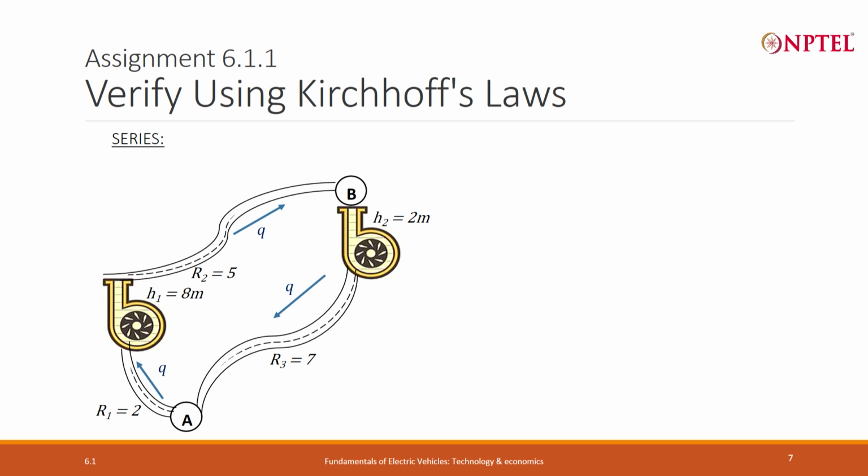But you do not have to remember that. If you just know Ohm's law and Kirchhoff's first law and Kirchhoff's second law, then the same method that we used in the previous slide, you can adopt that to compute the flow, and that is actually the way for you to verify that the total resistance is equal to R1 plus R2 plus R3. So, you can derive this relationship without knowing this relationship if you know Ohm's law, Kirchhoff's law 1 and Kirchhoff's law 2.